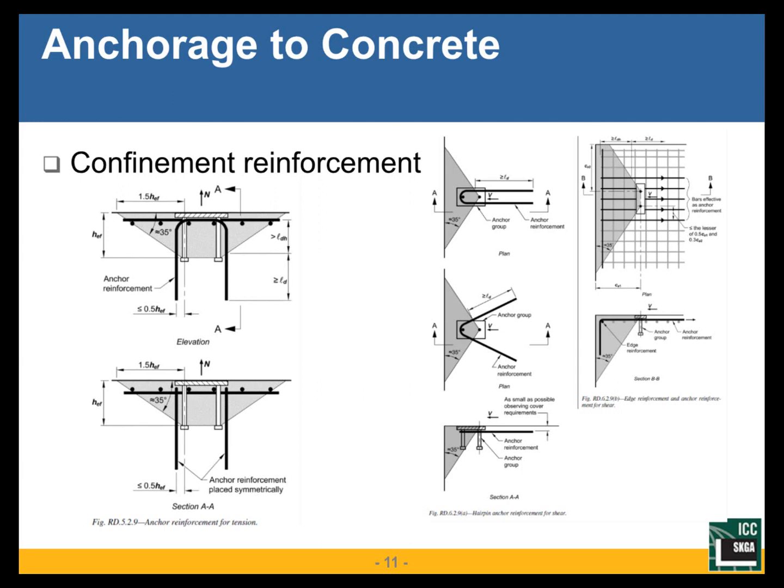And so this slide is labeled confinement reinforcement. It's probably also appropriate to call it anchorage reinforcement, because these are options on the left to provide anchorage reinforcement to develop tension to avoid the limitations of concrete breakout.